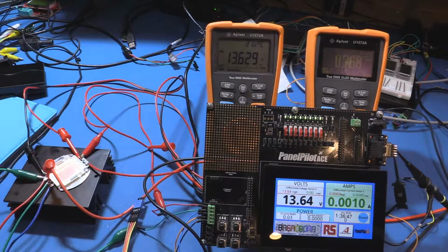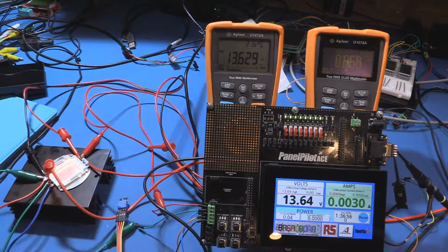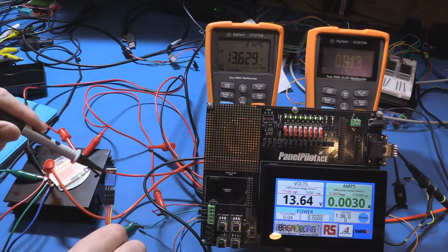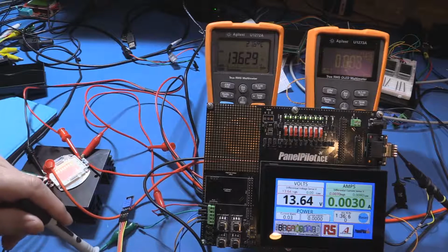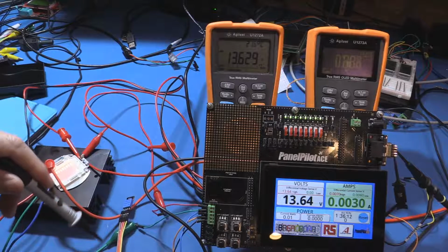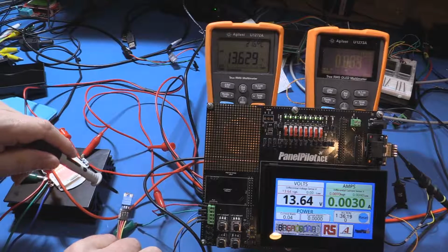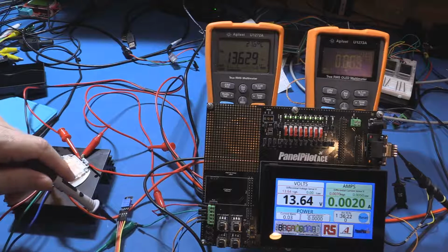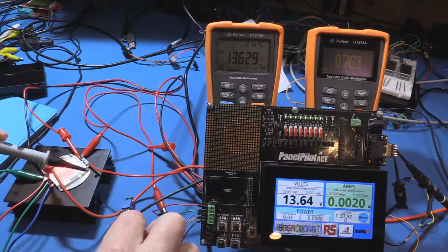Now the ground of the PanelPilotAce, which is the common analog ground, I've actually got connected further down, so there's a lot more wires. I've got the negative return, which is this red wire, going along numerous connections here through this 100 milliohm 4-terminal current sense resistor. It's one of the Vishay ones that they kindly sent me, and the other side of that is going through little skinny wires up to the analog input of the display for measuring the current, which is on the inner 2 terminals of the 4-terminal resistor. Then the yellow wire out of there is going to the negative side, via more little crocodile clips and various other clips, up to the return for the power supply and the other end of the meter.